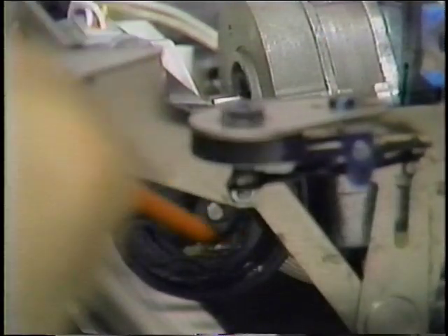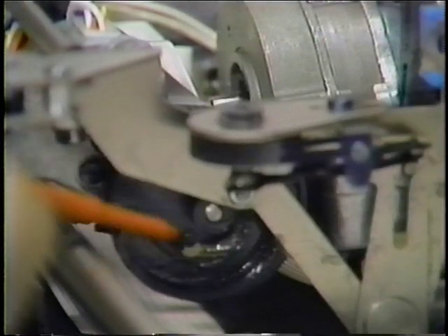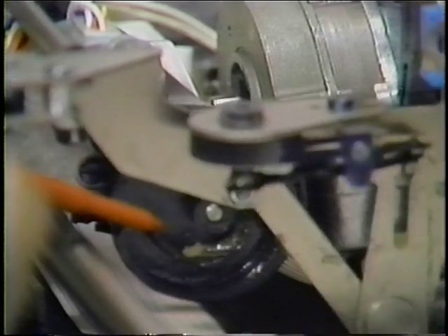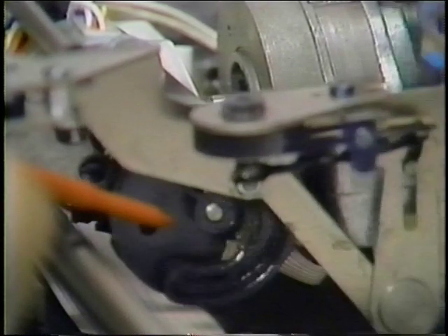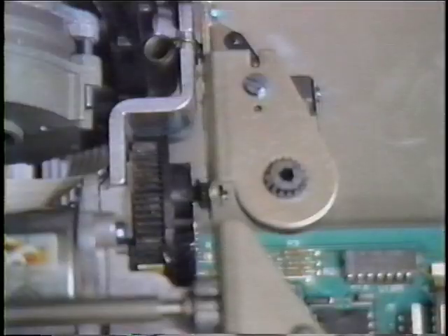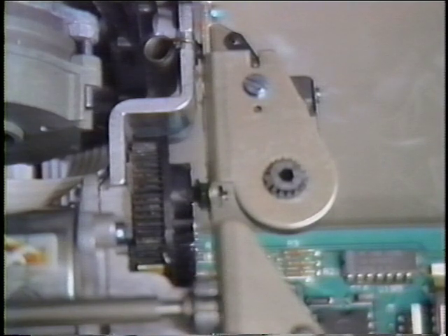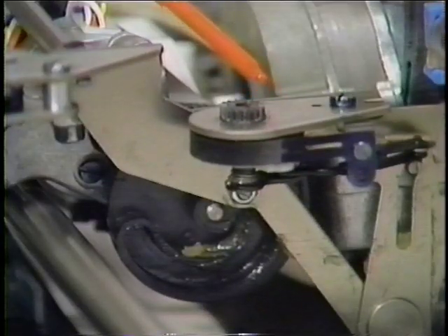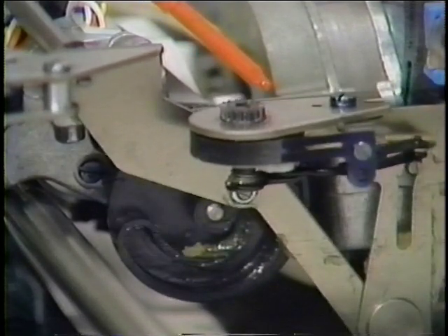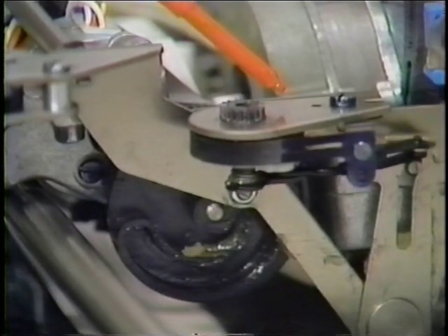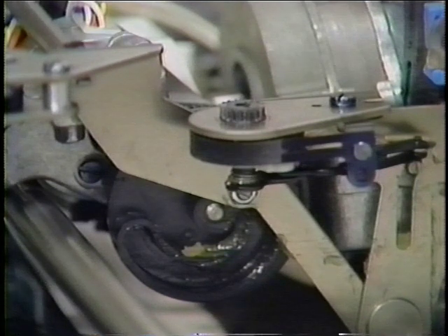Now let's see how ribbon lift and feed work. When a print operation starts, the ribbon lift cam is driven counterclockwise by the ribbon lift motor. The camming surface on the lift cam transfers motion through the ribbon cam follower to the ribbon plate. This motion lifts the ribbon into the print position. How far the ribbon lift motor drives the lift cam is controlled by the printer board.